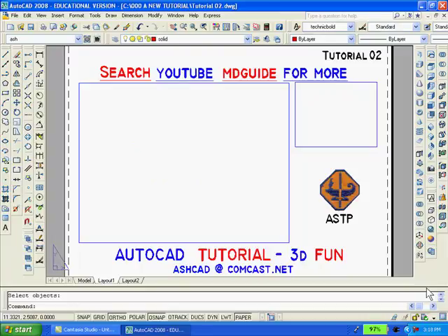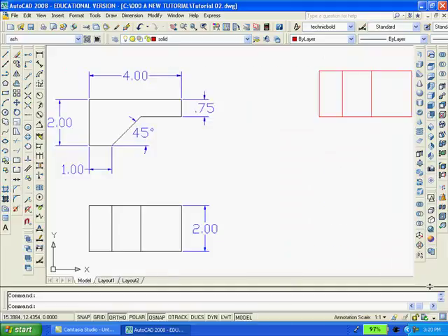All that remains are two rectangles which I drew previously to serve as templates for when I redraw the viewports later on. Also, the Layout 1 button is still activated, so we are still in paper space. To get back to model space, I will now click the Model button. With that accomplished, notice that both drawings still exist in model space even though they were erased in paper space. Now I will erase both drawings from model space so that I'll have the room to redraw both the 2D and 3D views.